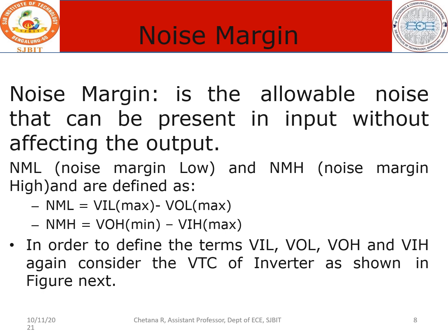The noise margin has two different representations, NML and NMH. NML is defined as VIL maximum minus VOL maximum. Similarly, NMH is VOH minimum minus VIH minimum. These are the terminologies equivalently represented for NML and NMH.